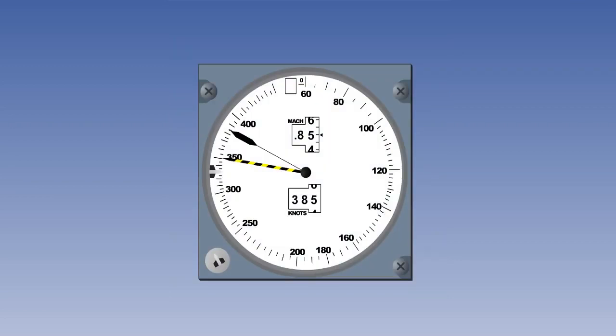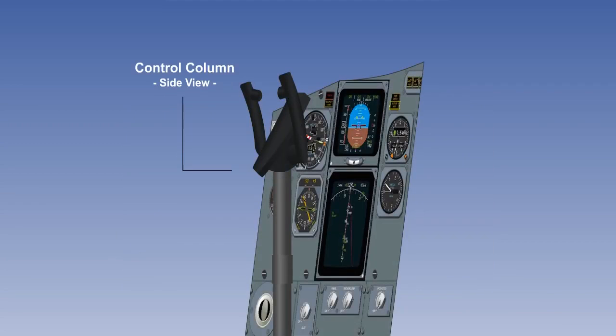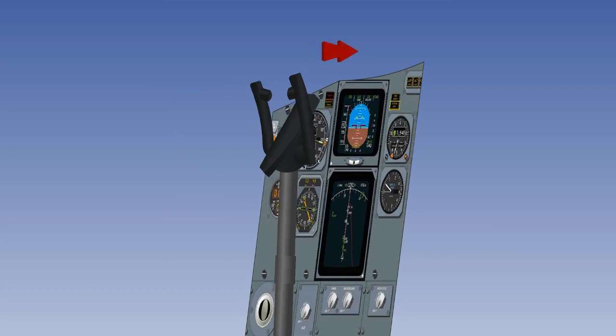During this lesson, you have learnt about high-speed and low-speed aerodynamic warnings. The first thing to be looked at was the overspeed warning and the indication provided to crews. Then you were shown the stall warning system and the different ways this is indicated to a crew dependent on how modern an aeroplane you are operating. Next was the stall protection system, how it differs from stall warning, and the different ways it is presented to the crew dependent on the age of the aeroplane.